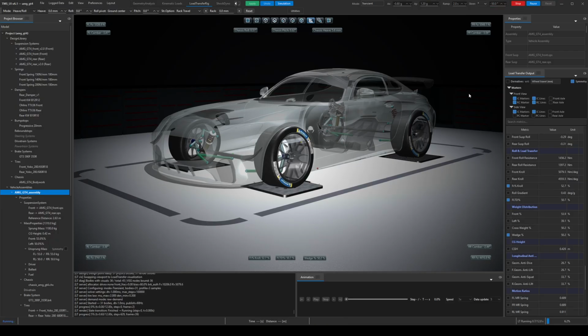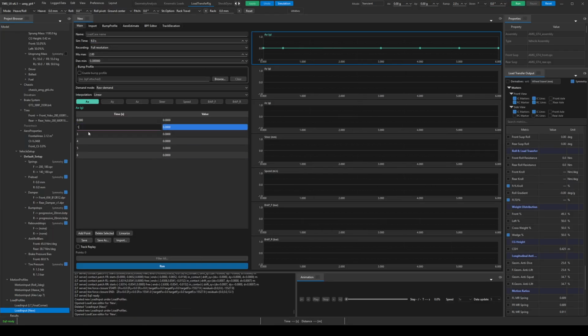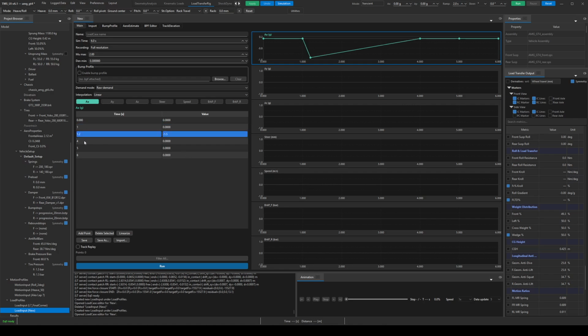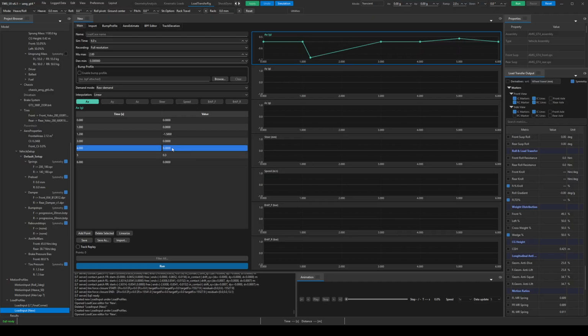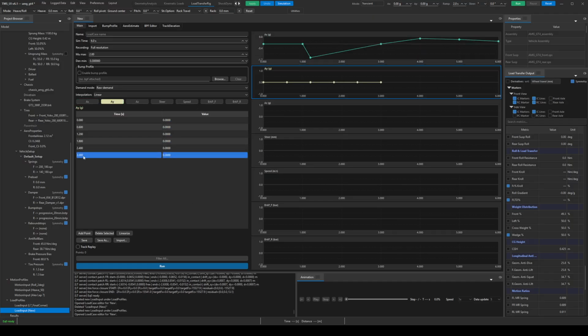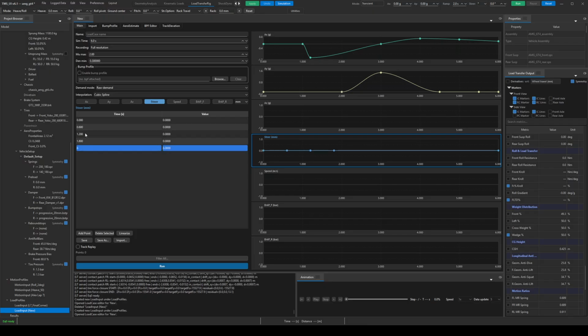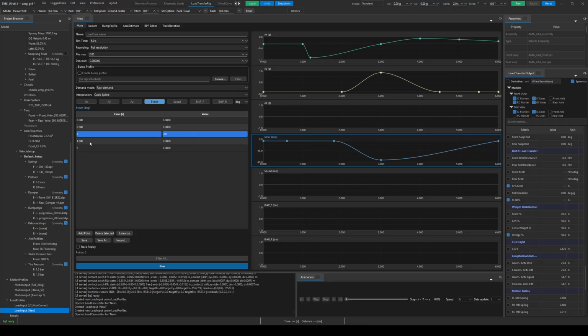For a more detailed study, the user creates a load profile. Right-clicking the load profile in the project tree opens the load input editor. It follows the same general logic as the motion input editor, but here the x-axis is time or distance, and the inputs are accelerations rather than imposed suspension motions. Creating a manual load input is simple. The user sets the simulation time, adds ax, ay, and optionally az points, adds steering points, and saves the file.